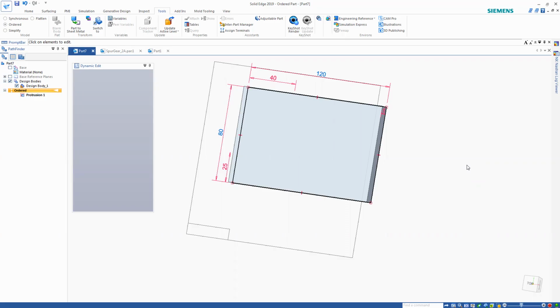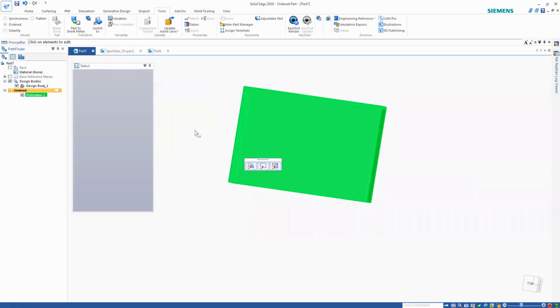And after that, maintain that one. And if you want to write some relationship between parts, don't change the part name and also the location. Don't finish everything at once and then start defining the relations between the two variables. But when you start doing that, before you conclude, test it by changing some values, whether they are really going to function, right? So that way you should be able to manipulate most of the things.